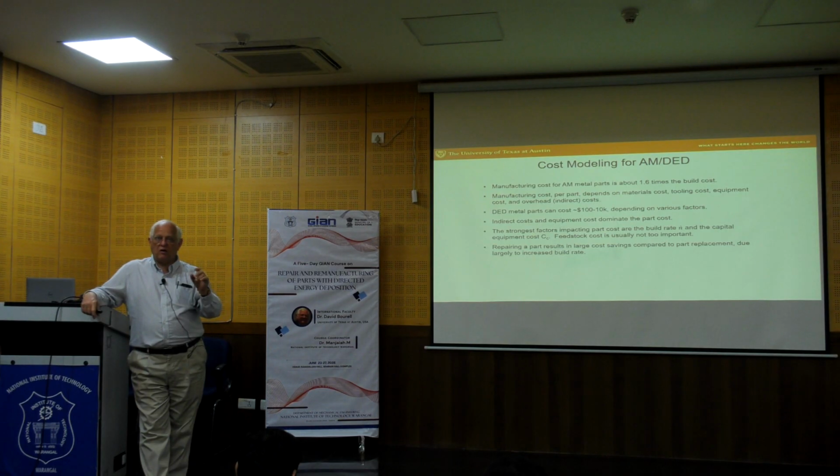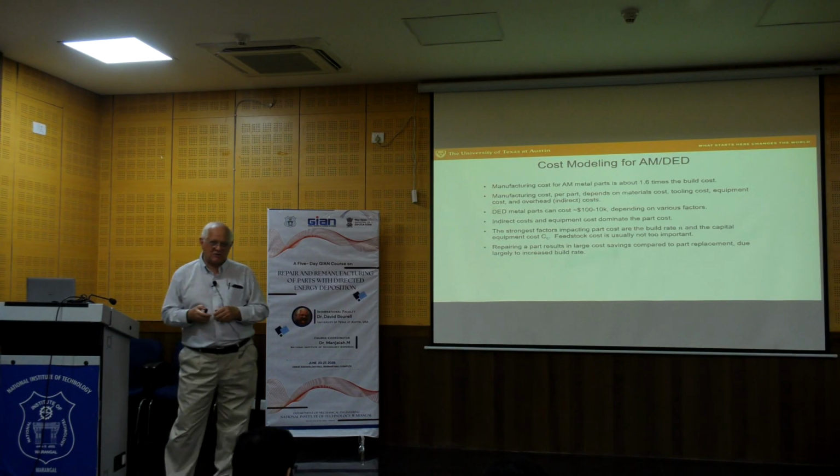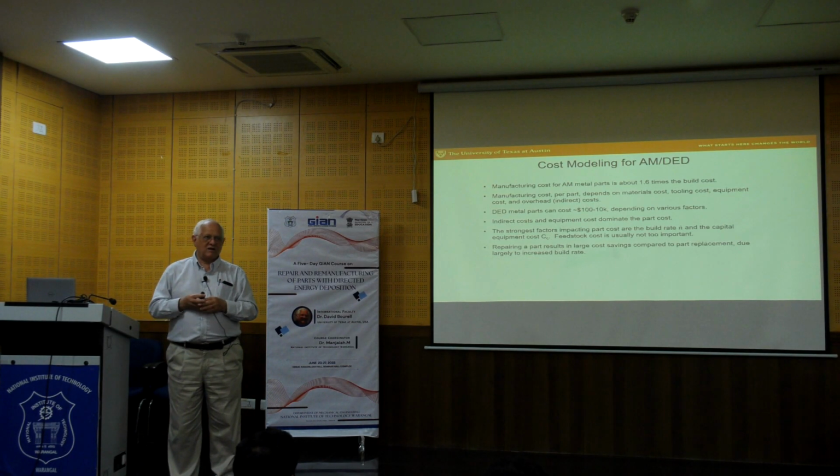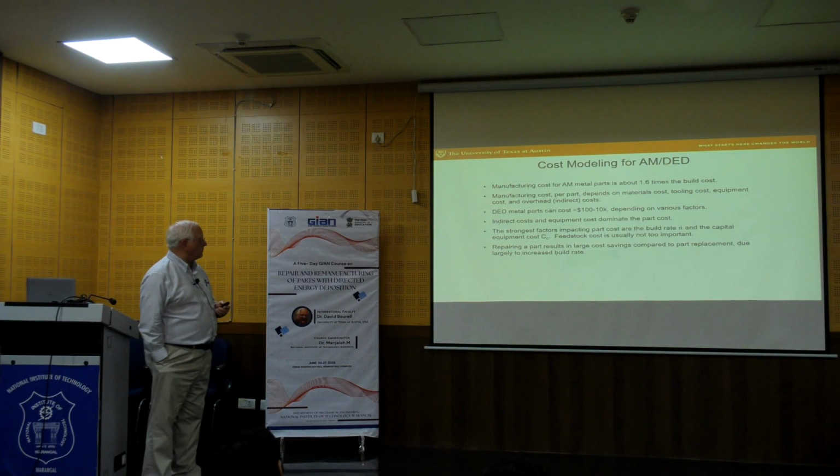If I'm doing these small, 1, 2, 5 kilogram builds, the material cost is really a pretty small fraction of the total cost. Now, if I'm doing a 200 kilogram build, then it's a completely different picture, and the material cost can become very important. But the takeaway is that, generally speaking, the material cost typically is not the showstopper on the cost of the part. It's typically the equipment cost that drives the part cost.